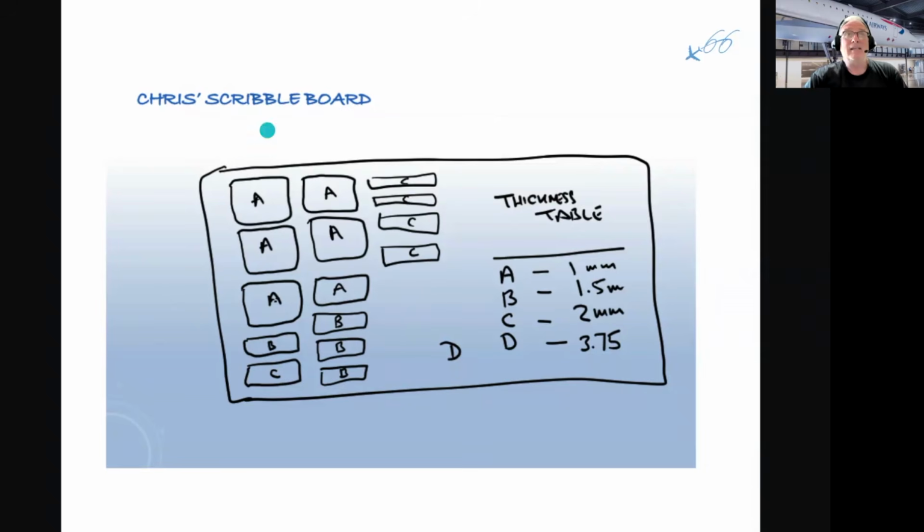So they start milling out these areas, and you have a thickness table with the different areas. Okay, so you've got the nice and shiny outside, which has the damage, and the milled out sections on the inside, which has the limits. And you have to match up both together, and that's where it becomes confusing.